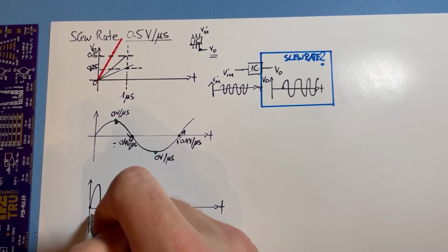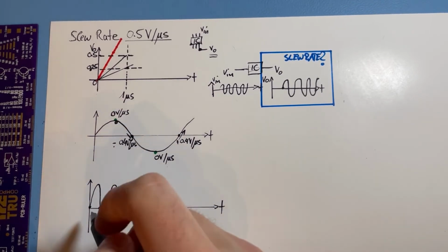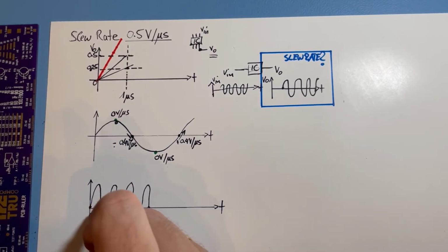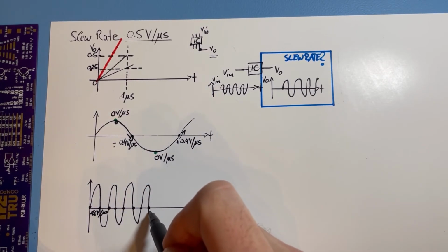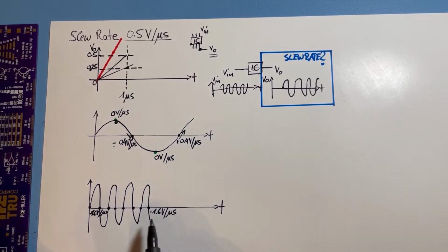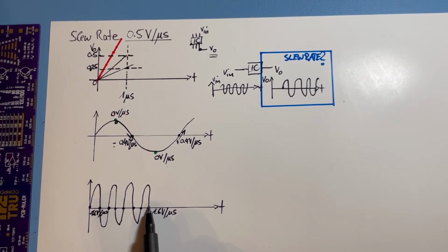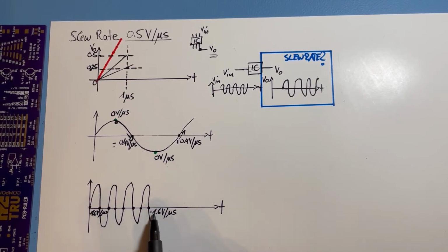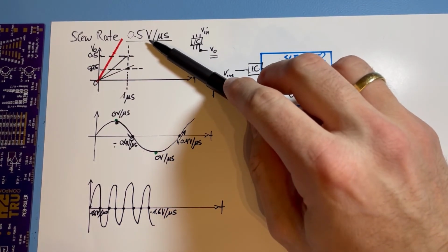So this goes to negative, let's say minus 1.6 volts per microsecond. And here again, the last point is also minus 1.6 volts per microsecond. So we would have such steep crossings, the voltage changing so rapidly at 1.6 volts per microsecond, that we cannot support it. Our output cannot follow here.